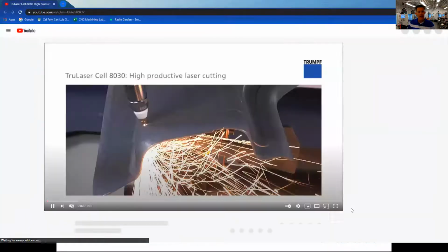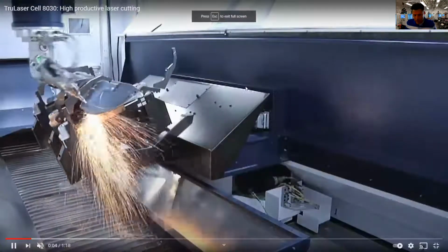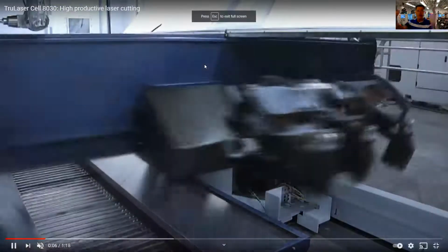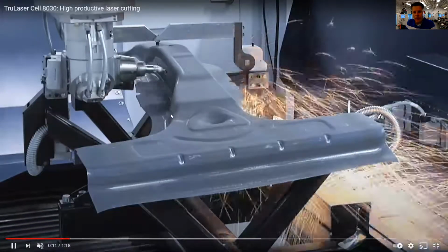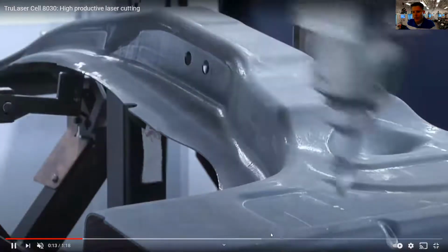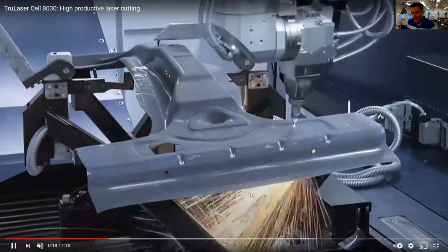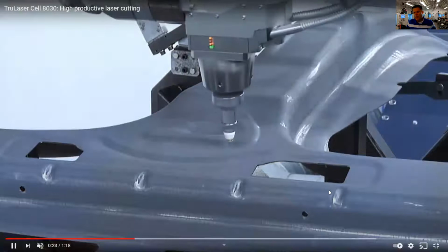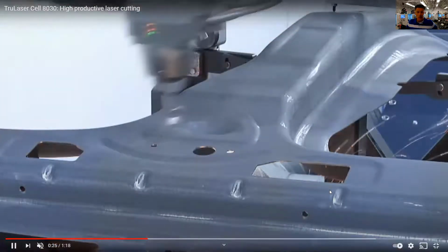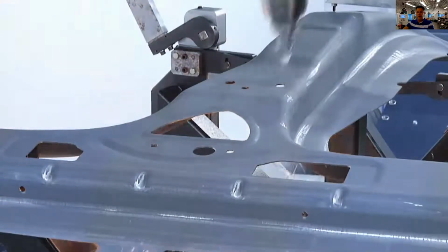Now this last one is a 5-axis laser cutter cutting unibodies for automobiles. So what this is doing is, if you have a bulk deformation, you have a stamping. So you have your sheet metal stamping, and you've got to trim it before you put it into the automobile and put the holes in it where it needs to go. But you'll see a lot of this material was held there just for the stamping operation. You've got to trim it and get rid of it. So what this laser cutter is doing is trimming the basically unibody stamping.